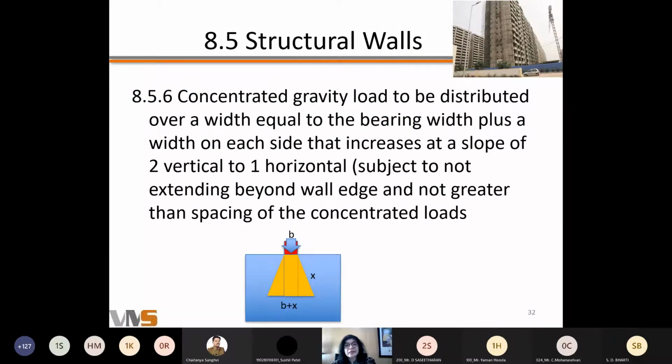And then there is this very interesting thing which has been discussed about when you have gravity loads, what is the amount of the wall taking them? Very often I find that you have beams which are 200 wide, carrying a lot of load, and then they come onto a shear wall in the weaker direction. So actually they are only on that wall of, let's say, 200 mm thickness. So sometimes there is a huge amount of bearing stress over there. But people just assume the whole, very long wall is taking it, when the gravity load is only going to that point, at that particular location in that floor, and it can only spread so much.